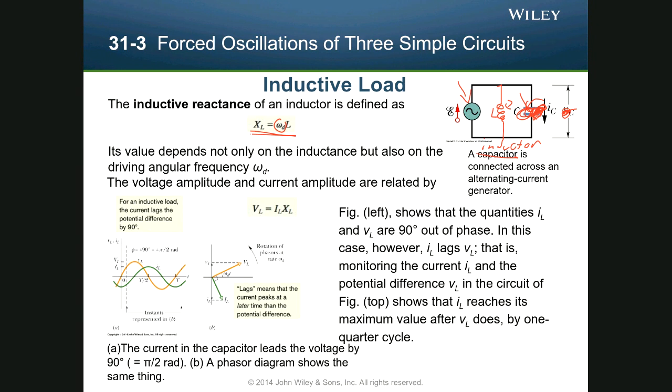What this will do is allow us to look at the voltage across the inductor. The unit of reactance is ohms, so we'll be able to use an Ohm's law sort of version of this and say that V_L equals I_L times X_L, where X_L is that inductive reactance.